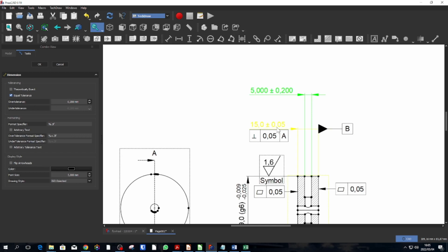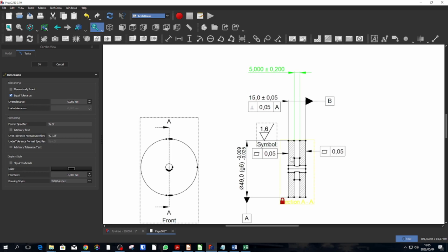So you can notice that for the depth of the flywheel we had a reasonably tight tolerance, and that's because we don't want the flywheel weight to vary much, so we control the thickness or the depth, and we want the flywheel to be very nicely concentric, so we have a tight tolerance here of G6 tolerance, -9, -25 micron.